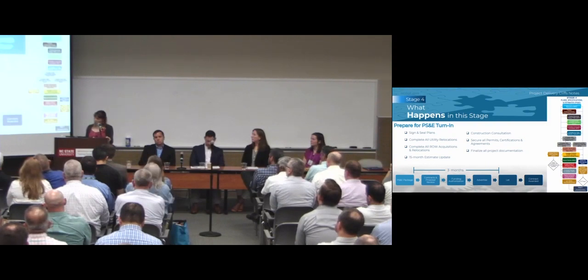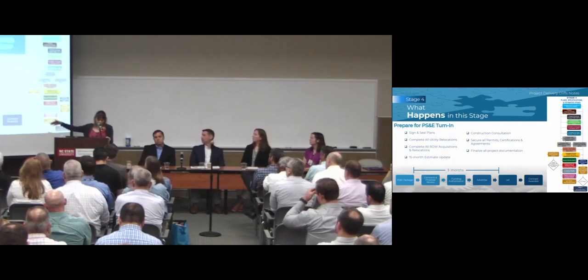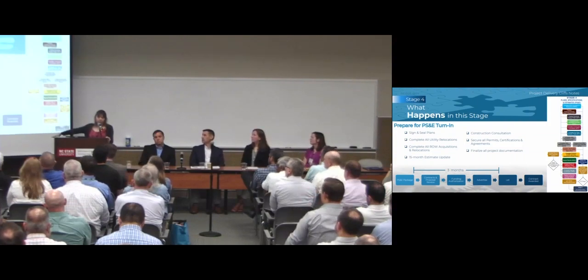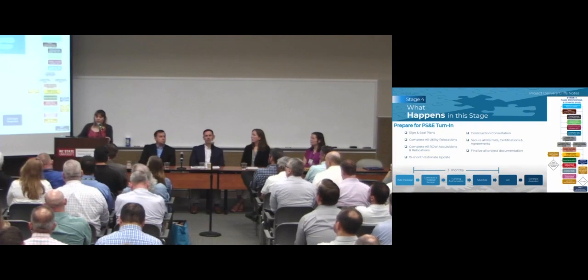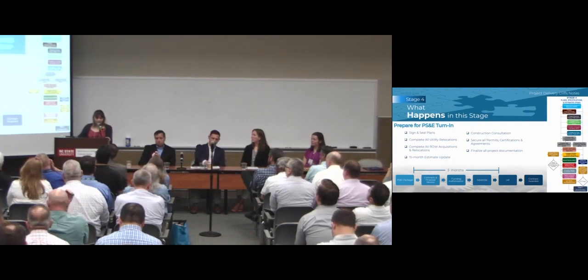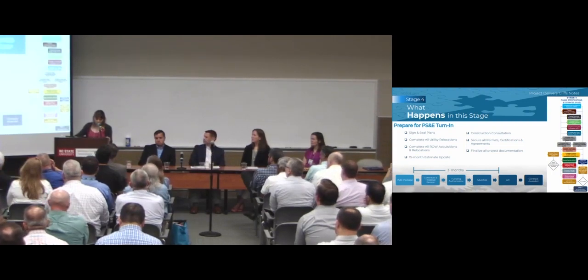It's important, this timeline on the bottom of the screen that you see here, it's important to submit the entire PS&E package 3 months prior to letting to allow contract standards time to do what they need to do. There's quite a bit that they end up needing to do. They have to review the plans and the supporting documents so that they can request and secure construction funds, develop the contract time, assemble the proposal, and advertise the contract package.